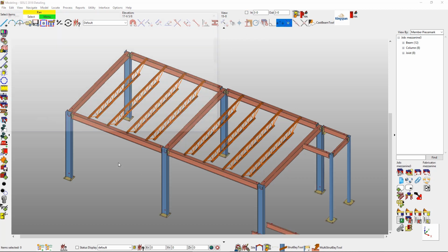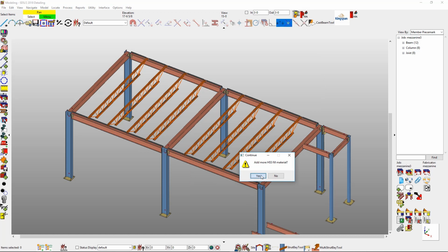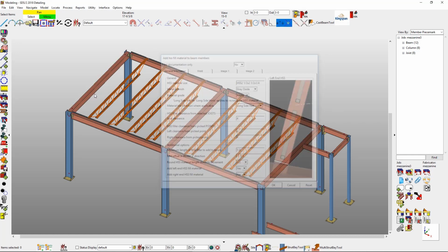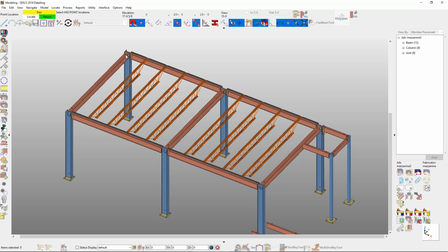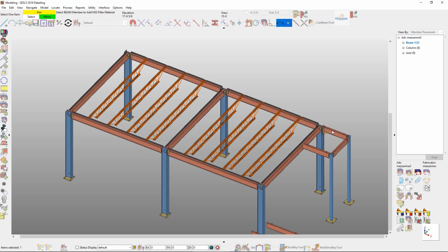Once all the structural members are added into the model, then you can go back and add in the secondary steel. These common items can be outriggers, hung lintels, curb angles, and a number of other items found in your structure. SDS2 uses both components and parametrics to add in these members. These can even be customer-written macros that allow for many variables that your company needs. The dialog boxes can be created by the customer and can be modified from job to job.